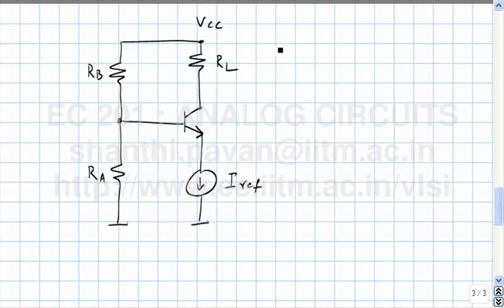What is the quiescent voltage here? Be a little careful now. Let me call that quiescent voltage VB. Can you estimate what VB will be? Do you need to know anything about the transistor or you don't? I need to know IB. Okay, so let us assume that we somehow figured out IB. So VB will be VCC times RA by RA plus RB.